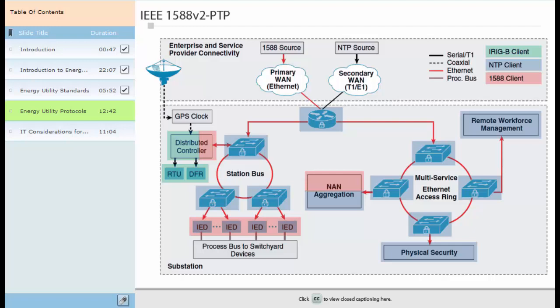Fault recorders record power faults and disturbances. They generate a timestamp when an important event occurs. Events are recorded at the substation and are transmitted to a central location for analysis. Accuracy to within 1 millisecond is typically required for this. Sequence of event recorders produce a chronological list of state changes within a monitored device. State changes are time-stamped and transmitted to a central source for real-time or post-disturbance analysis. To compare which event occurred before the other, timestamps of 1 millisecond accuracy are required.